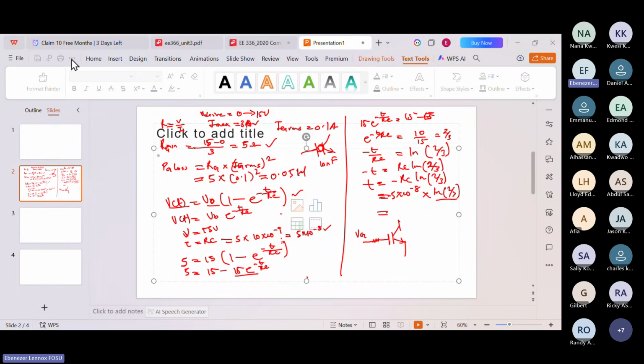We know that T on is equal to duty cycle times T, so the duty cycle is given by T on over T. When you look at the waveform, T on is the time that the IGBT is on, which is 0.3 T. Some of you, if you don't take care, might pick the 0.7. So please be careful. Understand the waveform before you pick your duty cycle.